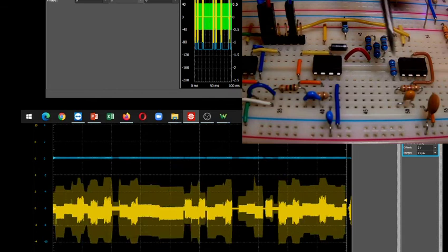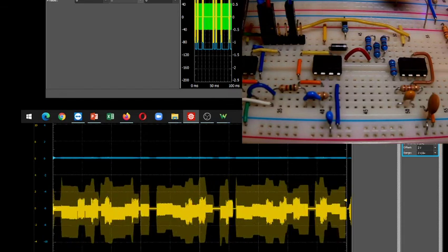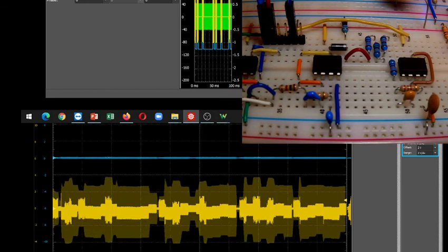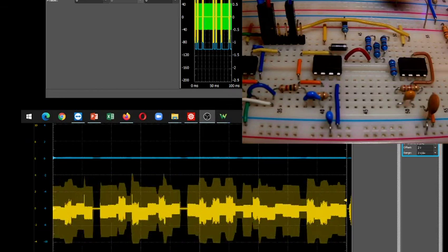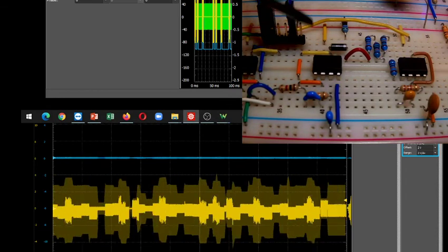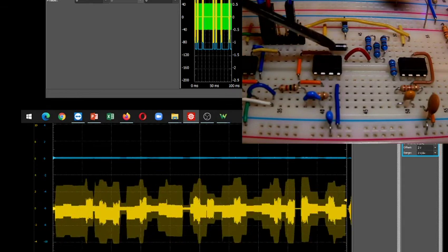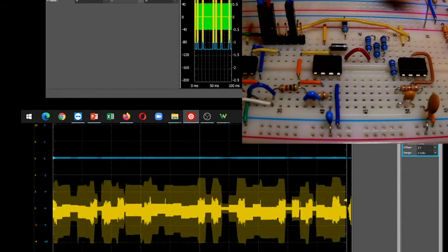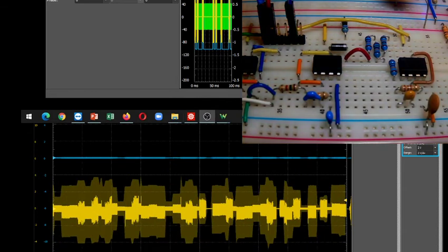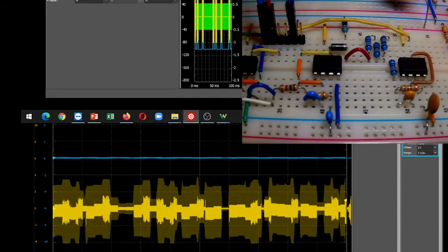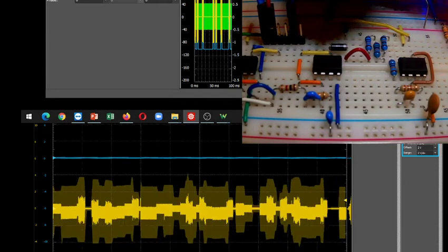High-pass filter, joined with the low-pass filter, forms the band-pass filter. The output of the band-pass is connected to a diode to rectify the modulation. Look at the blue trace, for the signal before and after the diode rectification.